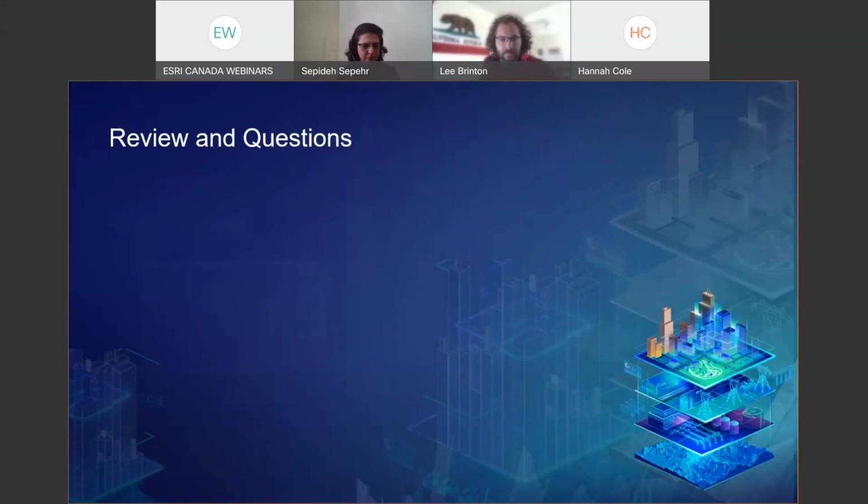Someone asked a question about georeferencing their Revit models. When you bring in a .rvt file into ArcGIS Pro, you'll see on your ribbon at the top of your screen that there will be a new option called, I think it's referred to as georeference, and that's something that you'll be able to follow through. And it's very similar to any other georeferencing method. You start creating and specify where it goes. One thing that I need to mention on that is it's really important that when you're georeferencing a Revit model, make sure that the scene coordinate system is in the desired coordinate system that you want that Revit model to be in. Otherwise, it'll take on the coordinate system of whatever you have, and it could be Web Mercator or whatever.